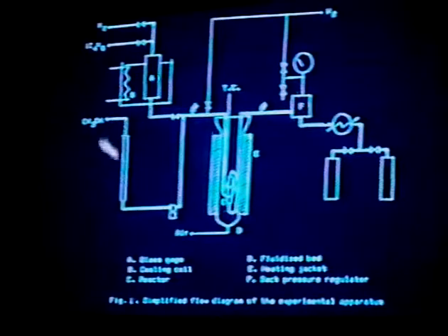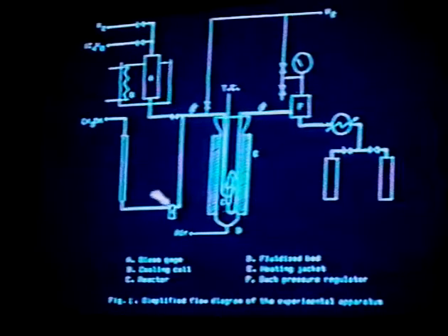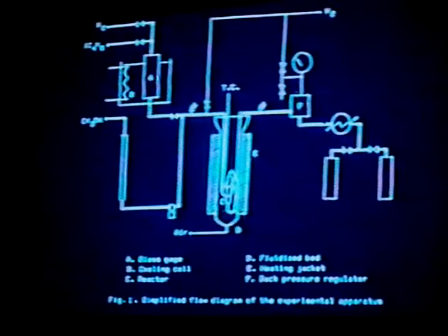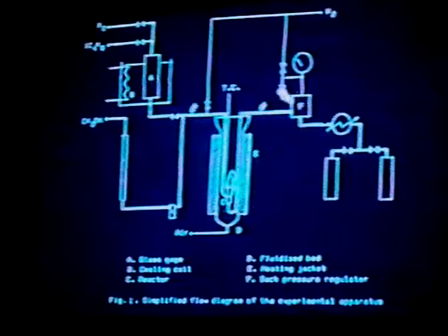The methanol was charged into a burette and pumped continuously to the reactor through a high pressure metering pump. The back end consisted of simply a diaphragm loaded back pressure regulator, a product cooler, and product receivers.